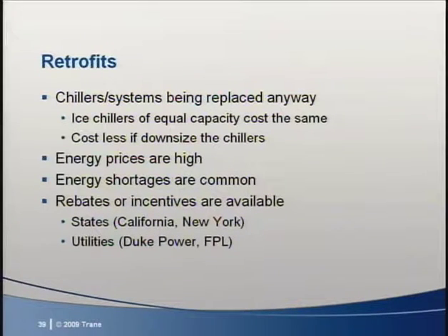While Fossil Ridge was a brand new school, chiller replacements are a window of opportunity for adding ice storage. Ice chillers are no more expensive than standard cooling chillers, but many chillers do have to be selected to be suitable for it. The total cost of the chillers can be less if they're downsized. And it's not hard to start thinking about an ice retrofit when energy prices are high or interruptions are common. Incentives are also available in both the public and private sectors.